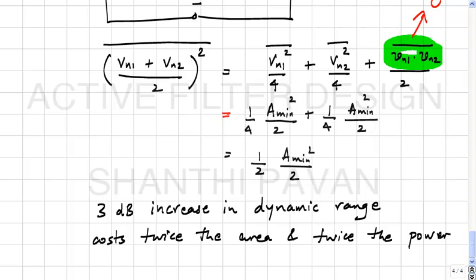I am now talking about two identical filters. So the question he brought up is, obviously you're putting in a sinusoidal tone. So are you putting the sinusoidal tone at a frequency well within the passband of the filter, or in the stop band? Obviously it doesn't make sense to put anything in the stop band because nothing is coming out of the filter.